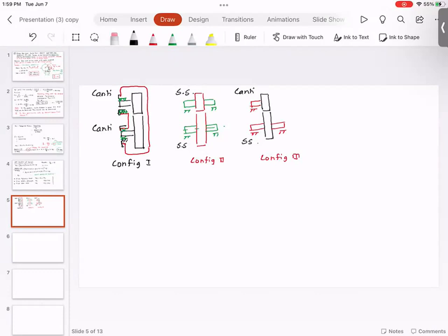And then clearly, depending upon the configuration, that shaft could be extended. So this is sort of a compact design, but please try to understand the amount of forces and the moments that are going to come on the bearing, because this cantilever is only supported on the left hand side. So the amount of forces and moments are going to be significant.